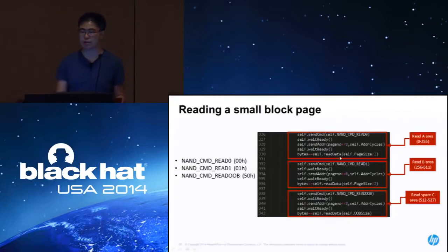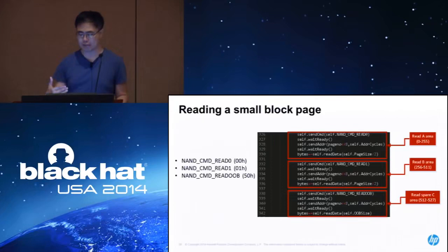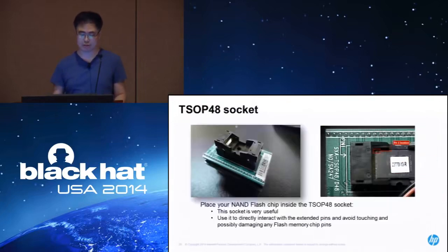If you go to this function, it's actually reading each byte, each page. But the good thing is that the FTDI chip itself will take care of all the underlying I/O and strobe operations, so you don't need to take care of that. That is one good advantage of using this FTDI chip, because there are some other attempts using Arduino to read NAND flash memories. I guess it will be more of a hassle because they don't support these basic functionalities that FTDI chipsets provide.